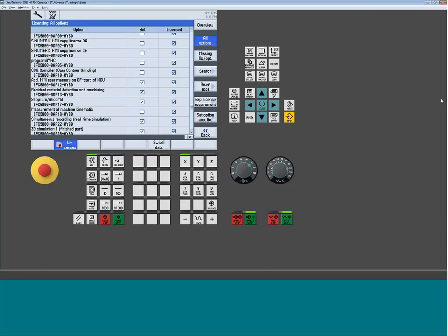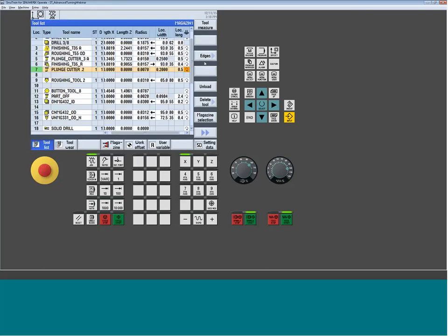Is tool orientation in the tool list still the same regardless of B-axis orientation? So I am expecting that you're referring to B-axis on a B-axis style lathe. It is. However, the one thing you've got to be aware of when you get on builders' machines like that, when they get into more of the 4- and 5-axis orientations, is they'll have a base position of the tool that's going to match the tool offset geometry.